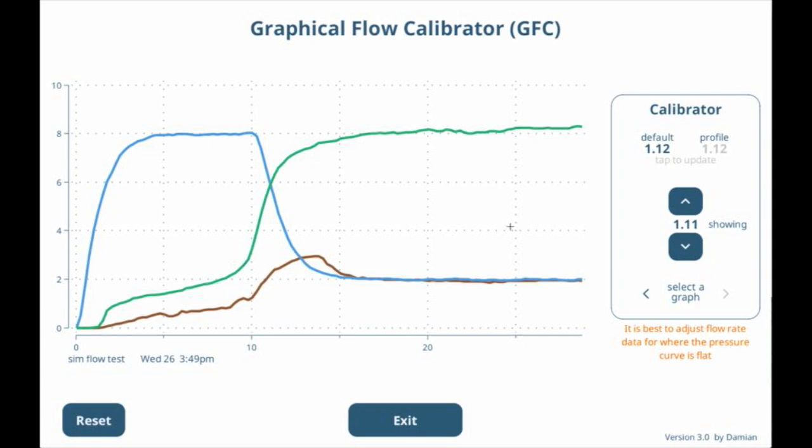The other area you might want to calibrate, though, is if you're using a pour-over profile and you might not have a portafilter filter fitted. You might have an open basket, or one of those filter baskets. In those cases, you pump water with zero pressure. So you might have calibrated at 2 mils per second at 8 bar, but at 2 mils per second with no pressure, that flow rate might be higher than the calibration. So you might find a new figure for that case.